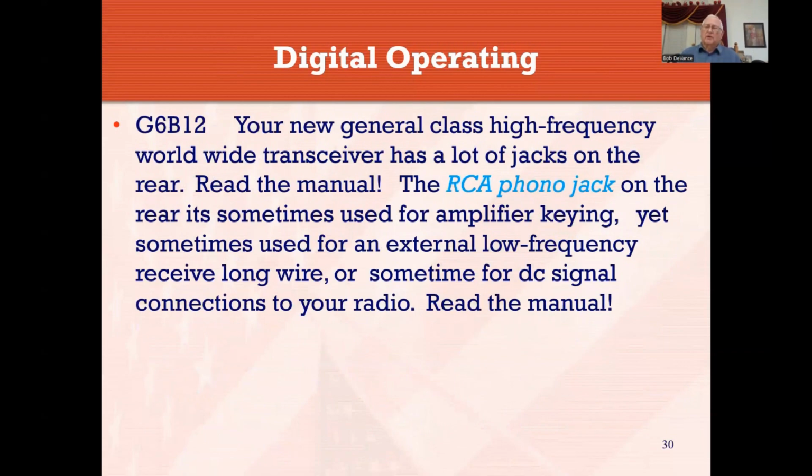RCA phono jack. Does anybody know what that is? Yeah, that's one of those little audio jacks, basically. Back in the old days when we had component stereos, you had a turntable with a cable that plugged into the back of an amplifier. Usually those plugs were RCA plugs, as they were called. They're low-frequency audio jacks. A lot of the backs of our radios will have that RCA jack on the back of it, used for amplifier keying. It's basically a control line to key your power amplifier on and off.